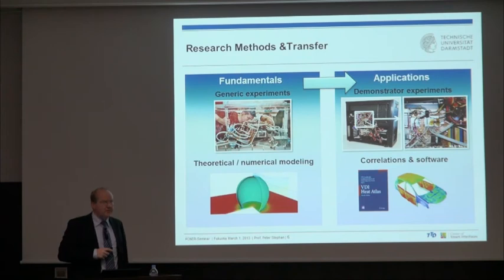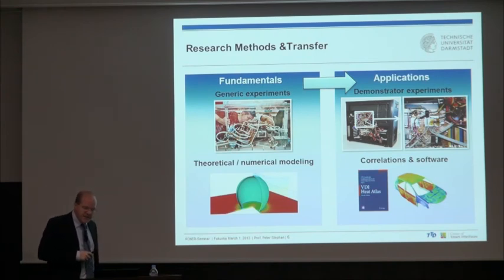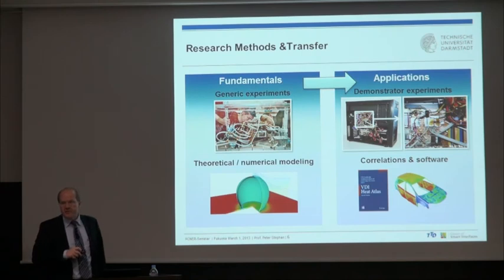We did this, for example, rather successful here. This here shows an example also of our institute. When I worked in industry and when I came to a university, one of our subjects was also drying of polymers, water-based polymers, basically paints of automotive industry. So we developed with generic experiments a numerical model, very, let's say, accurate models how to dry a paint using convective dryers plus infrared dryers.